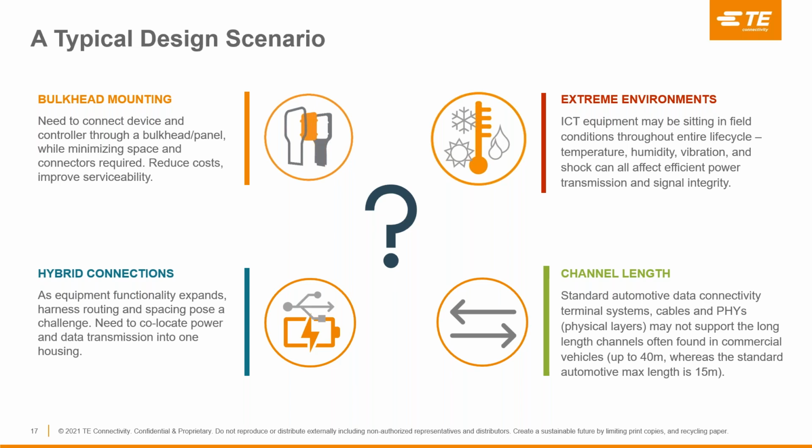When we look at extreme environments, minus 40 to 125 C, operating requirements for 365 days a year, outdoor usage for vehicles, we have to significantly address the need for more robust housing materials to withstand vibrations and the environmental conditions in terms of water ingress, dust, and dirt, and the constant exposure to the elements, not just water and temperature, but also the amount of dust and dirt that is created, for example, on a construction site.